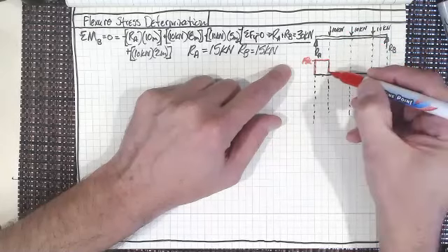We want to come up with some things here too to show how much we have under the curve at each of the different times. So if we look at this right here, I think everybody can see that we're at 15 by 2, so that's 30, right? 15 kilonewtons by 2 meters is 30 kilonewton meters.